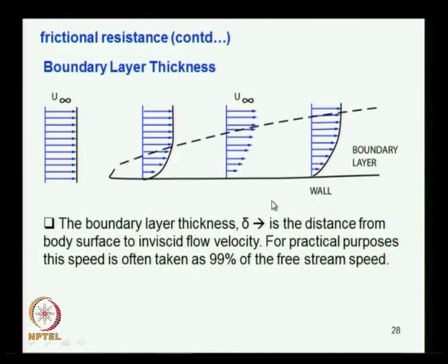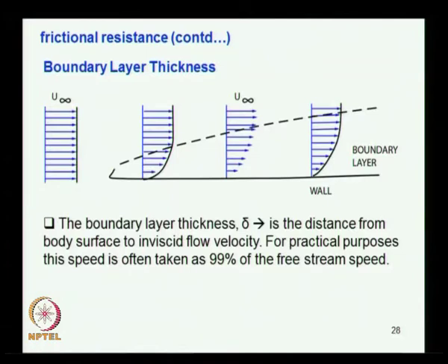There is no physical boundary there, it is only an assumption, so that it is easy to calculate or manipulate the viscous effect. One of the advantages is that if it is an ideal fluid, viscosity complexity can be avoided in the mathematical formulation. So you need to consider the real fluid cases inside the boundary layer, and outside the boundary layer often people deal with it as potential flow, where the formulation is rather easy and computation becomes less tedious. So that is the reason.